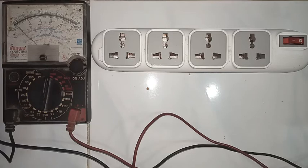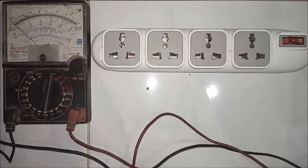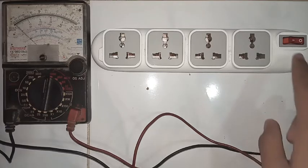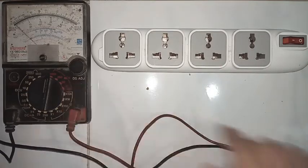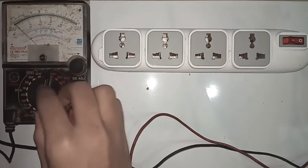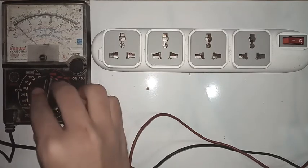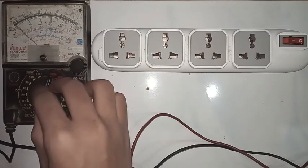Assalamualaikum and hello everyone. My name is Ahmad Hafiz bin Mahzan and in this video I will show you how to measure the voltage for an AC circuit or AC power source. AC means alternating current. For measuring, we will use a household power outlet as the AC power source and a multimeter as the measuring apparatus. Firstly, we will need to change the setting of the multimeter to ACV measurement. I will choose the 1000 volt measurement.